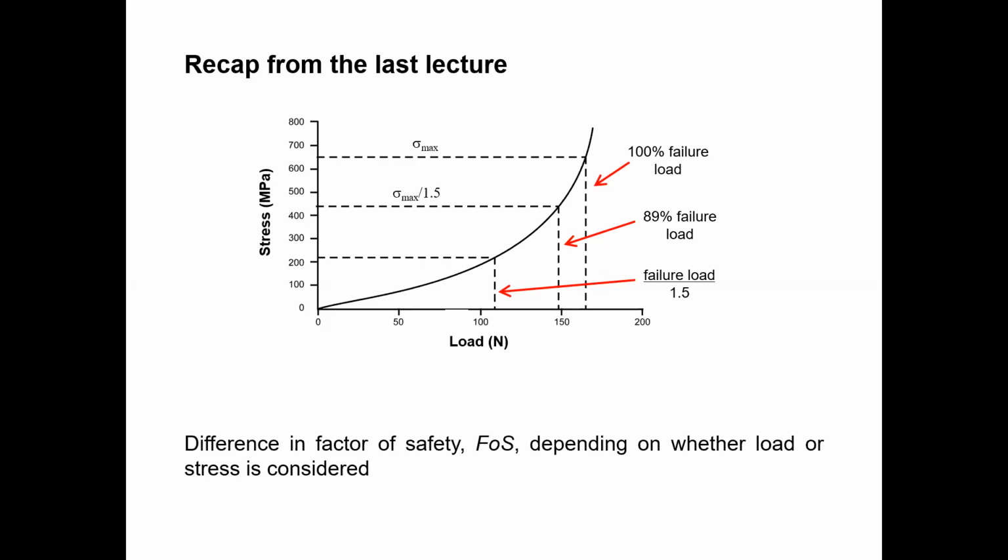And the curves cross each other. So assume the lowest value at 10 to the power 3 cycles is given by the groove, and the lowest value at 10 to the power 6 cycles is given by the pillar, something like that. Then you need to consider both points.